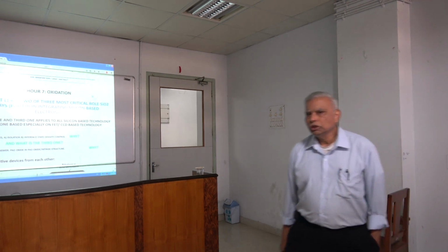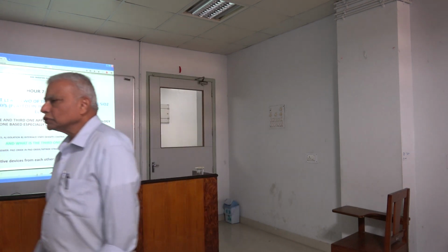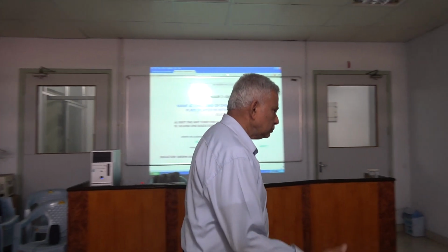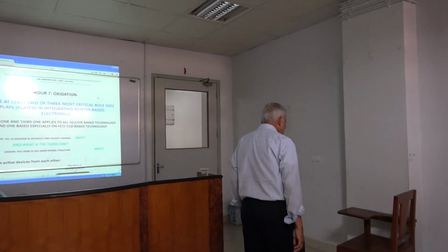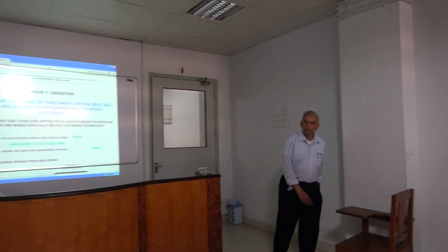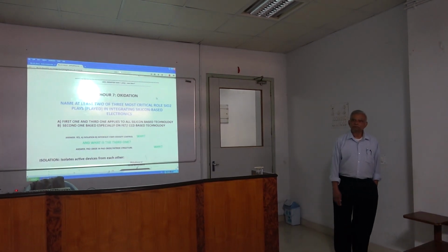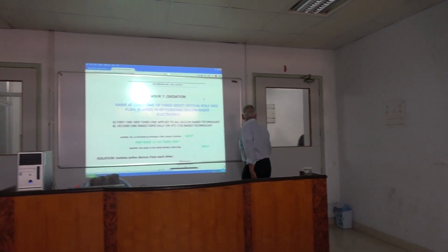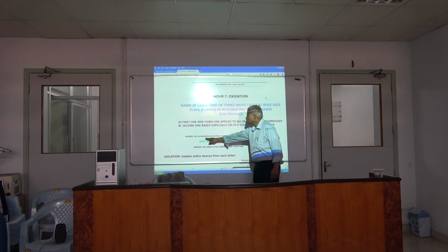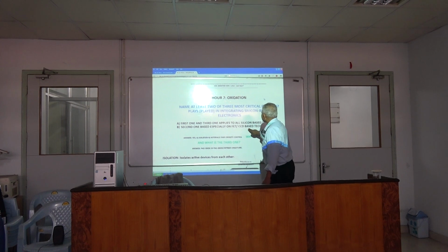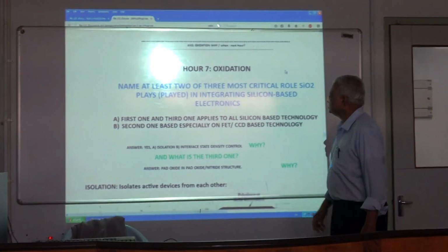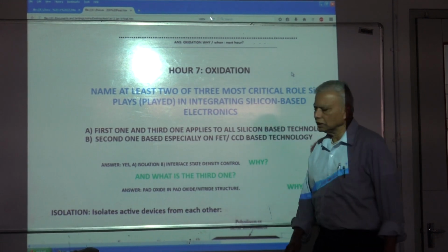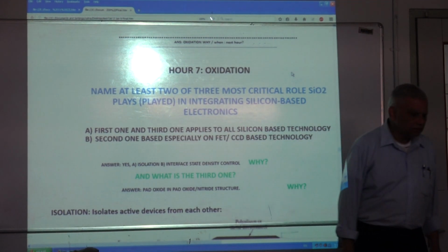Okay. And then we do other tricks to bring it down all the way to 10 to the 9 per square centimeter level, where it's not significant anymore and you can do the device size. So the trick of the trade, from the field effect transistor point of view, is that interface properties are extremely important on an atomic level, and oxide does the trick.